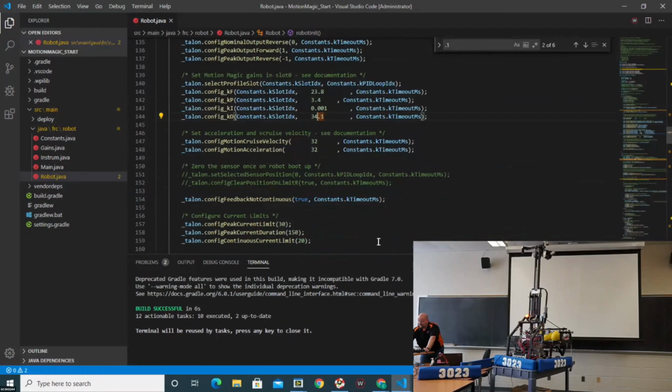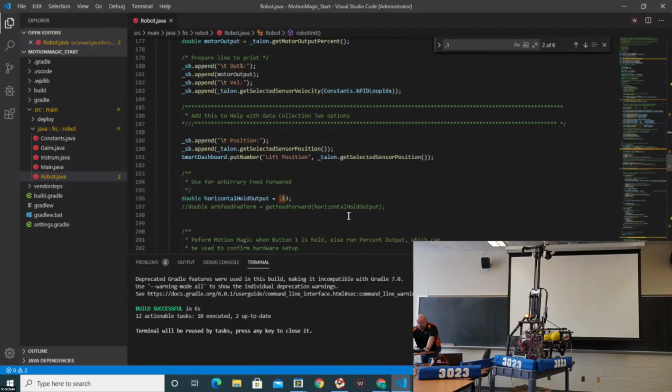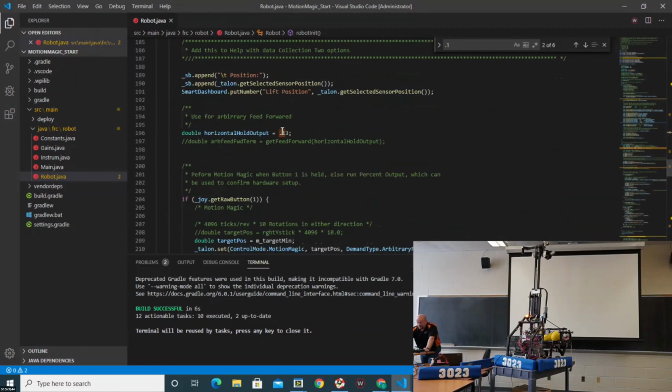What time is it? We got about 15 minutes left, so that's good. That's going to affect things here a little bit. And what that D term is going to do is really for that bottoming out. It's going to prevent us from overshooting. It's going to hold back the horse a little bit and soften that bottoming out there.